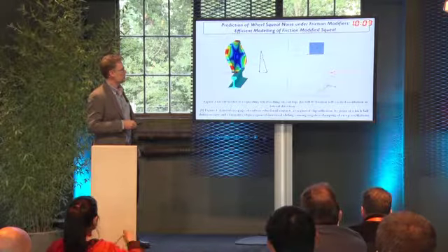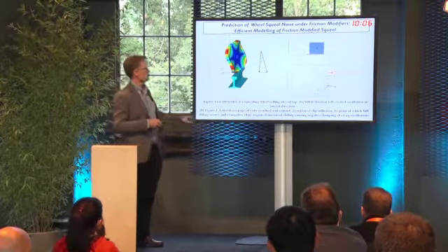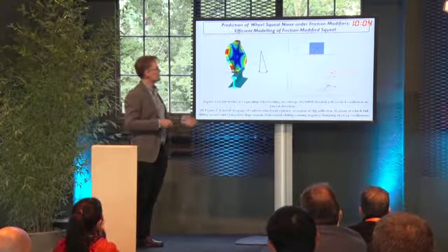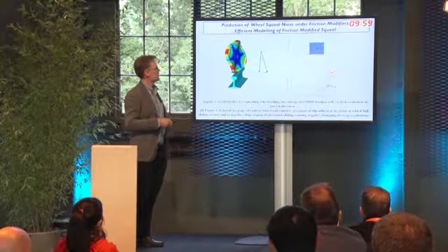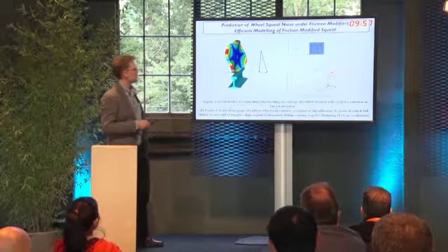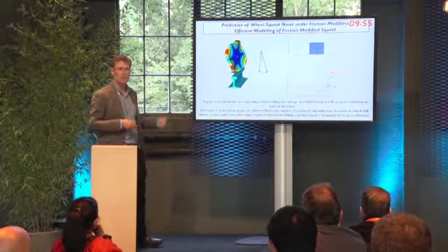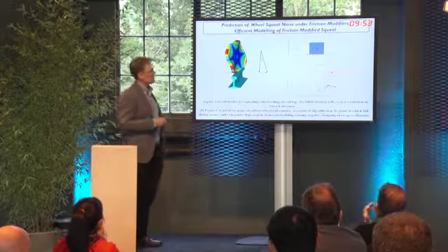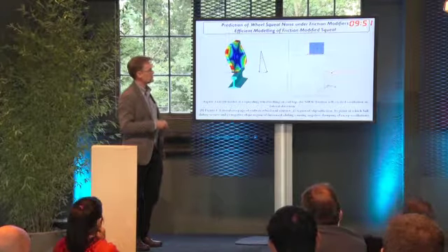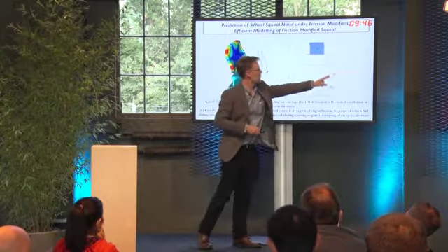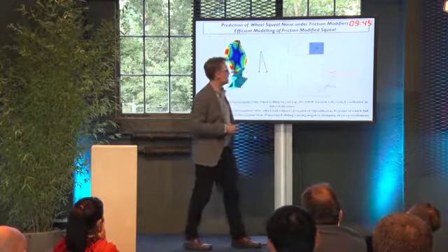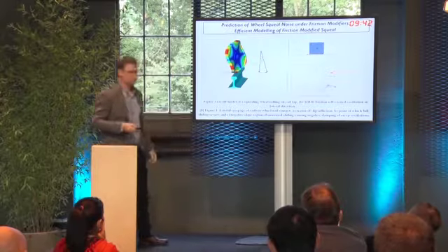So the dynamic model is shown here, our analytical model based on a single mode of vibration. This lateral mode, typically with 3 nodal diameters, is very efficient at transmitting sound, and it's excited via this lateral creep curve, in particular when you get over to this negative damping region.